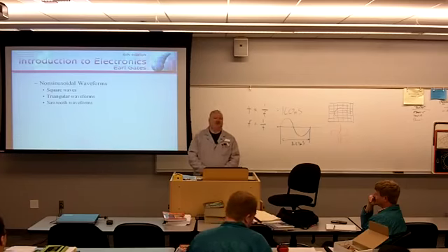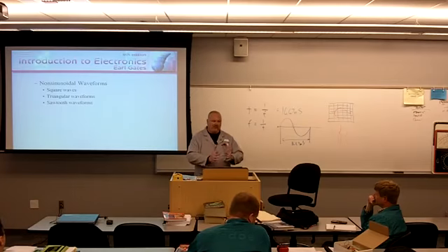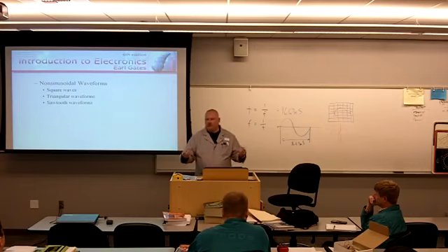Square waves, triangular waves, and sawtooth waves. All of these waveforms represent intelligence, and all of these are made up of harmonics, fundamental frequencies and harmonics added together, and that's how we create those things. That's how a function generator works. Internally, it adds all of that stuff up and then gives us the signal that we want.